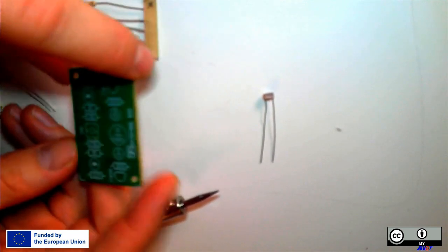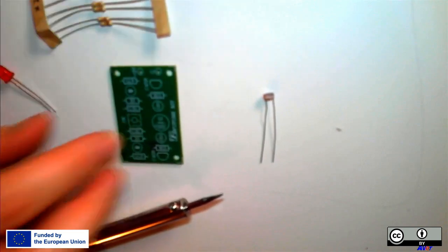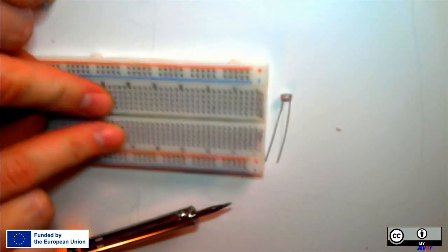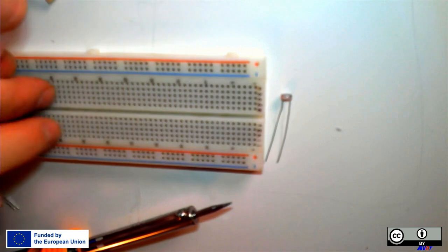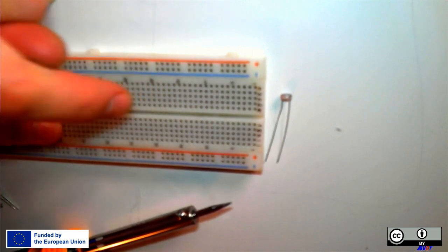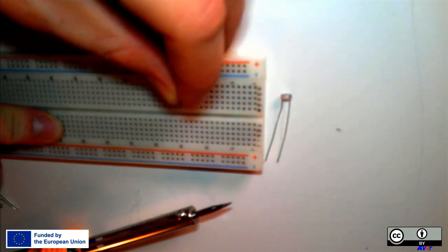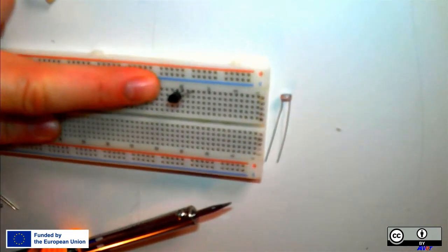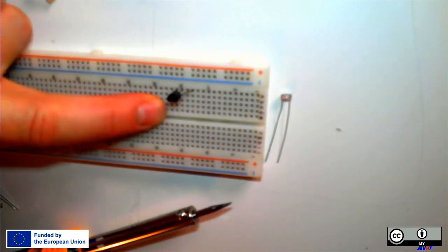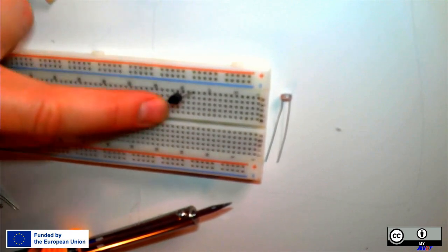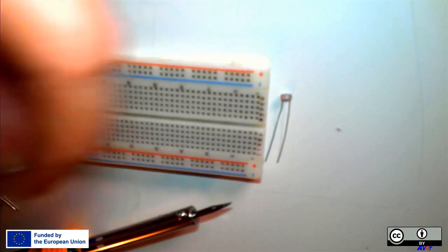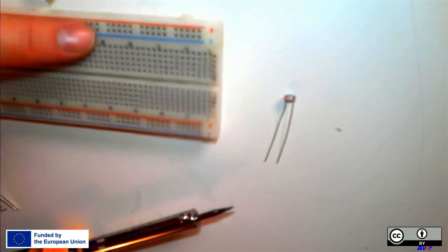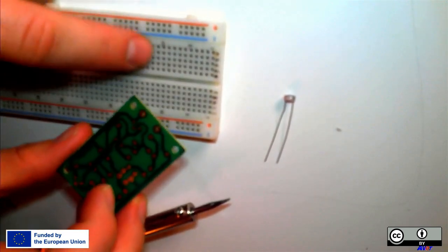Then we can use something like this, where we avoid the soldering. This is called a breadboard. We're going to talk a little bit about them later as well. Basically here we clamp the components because the entrance has a small clamp in it, where we can connect the components to copper wires or copper thread that lies beneath the plastic in a pattern. So this is really smart when we're prototyping, but for professional circuits it's much more common to use these, as the connection in breadboards can go bad. So we prefer this when we're moving into a more finalized product.